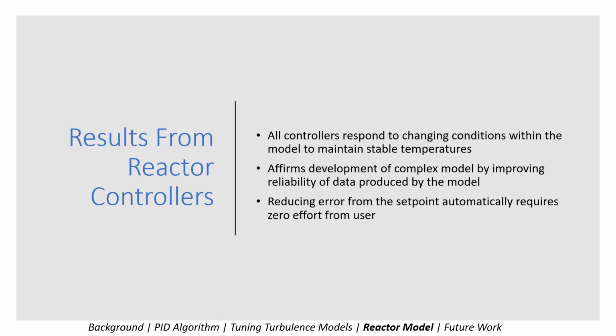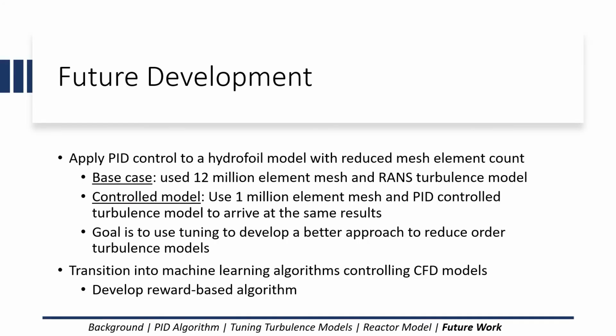This eliminates the need for constant input from the user and allows for a much smoother process when running the model and experimenting with different changes to the reactor. As mentioned, this is initial work for merging controls technology with CFD for responsive computing. The scope of this research continues to develop and look for more avenues where PID can be applied to CFD models. Current plans involve adapting a controller used on the pipe flow model to a hydrofoil geometry.